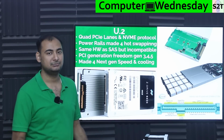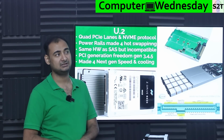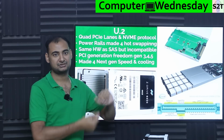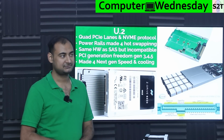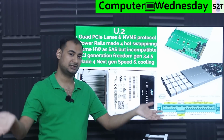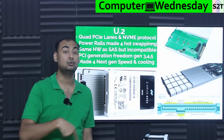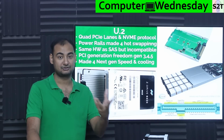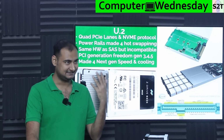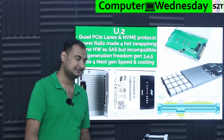So how can you communicate with the actual CPU core as fast as possible? You would think RAM. Well, yes, but RAM is meant for processing, as in it puts data there to crunch it. So what is the next best interface? Well, PCI Express. PCI Express is the interface that was designed to communicate with the outside world. CPU to outside world, PCI Express. Even networking and all that, generally it goes through PCI. So PCI goes to a controller that converts it into Ethernet or whatever have you, and then it goes on. Again, that's exactly how your South Bridge works. It takes a PCI lane, converts it, and voila, now you have SATA.